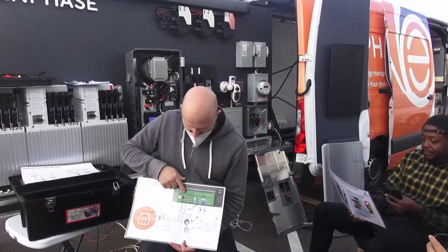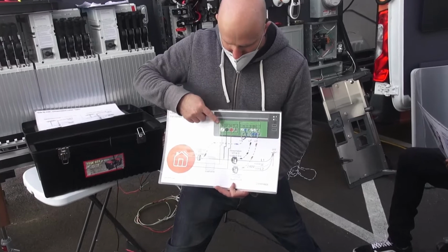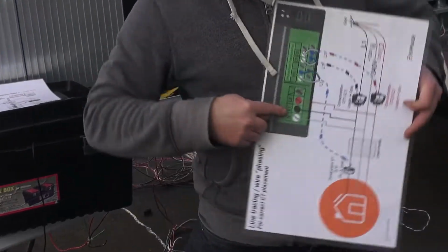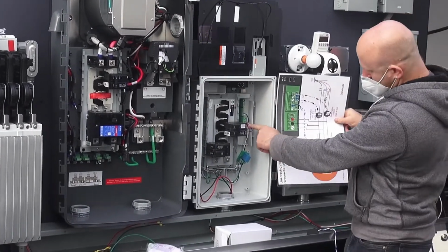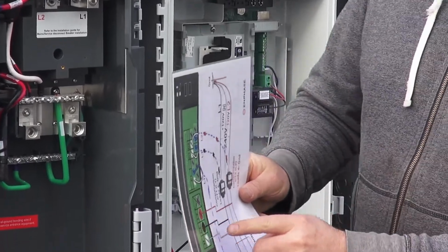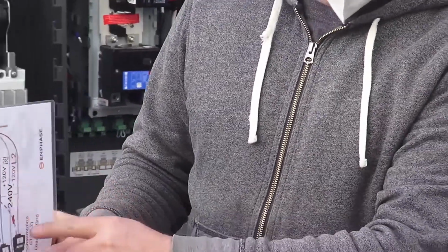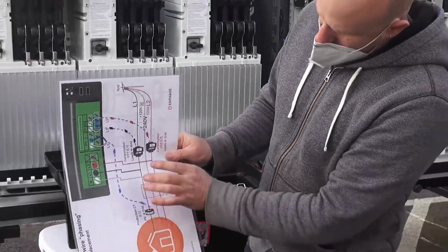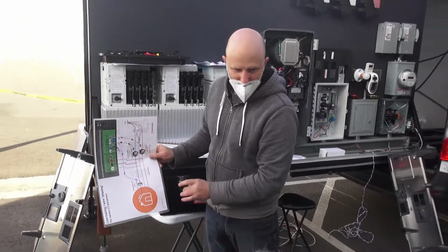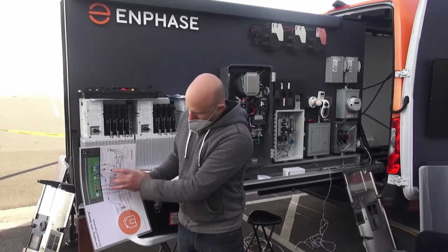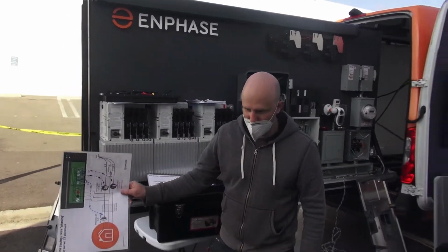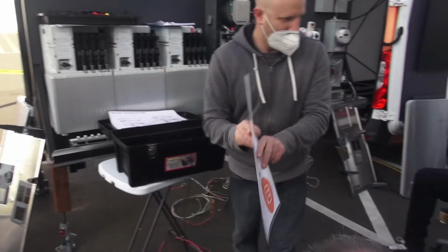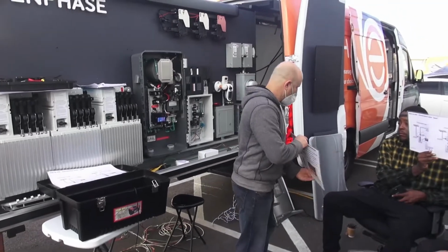Okay, so this is the same thing. I'm just trying to show you that when I measure from this terminal on the Envoy, L1, right there, and I keep on going elsewhere, I should always get 0, 0, 0. And then now I know where to put the CT. Before I put it on there, I'm going to take my probe and just make sure that it's live, right? Okay, cool. Does this make sense?